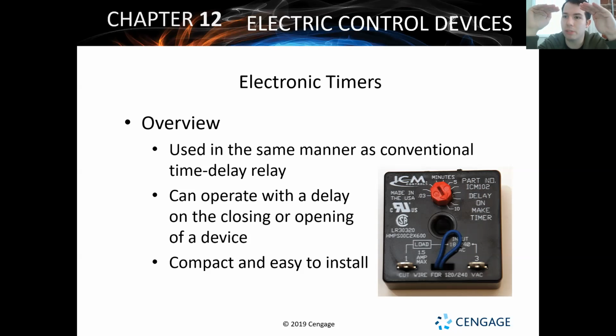You want to have it where everything's back at what's called equilibrium, where everything's the same. So if you have your gauges hooked up to a system while it's running, your high side gauge will be a much higher pressure than your low side gauge, obviously. You can hook your gauges up to a system when it's off, and the needles will both be at the same exact pressure. They should both be, let's say, 200 PSI. But once that system starts to run, you should see your high side go up and your low side pressure go down.